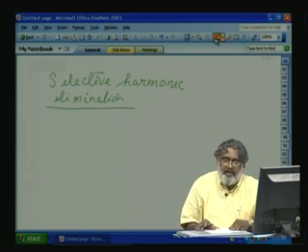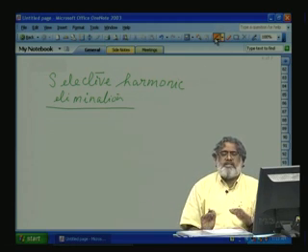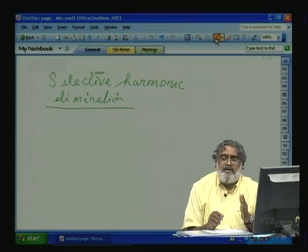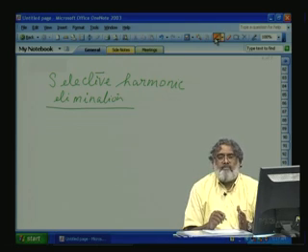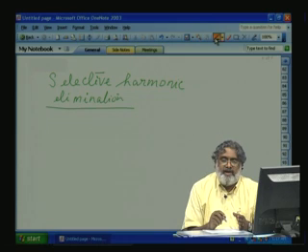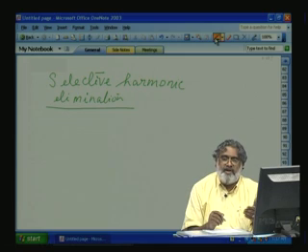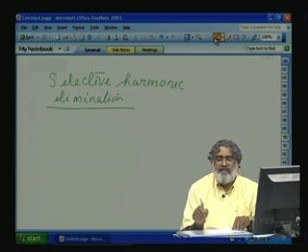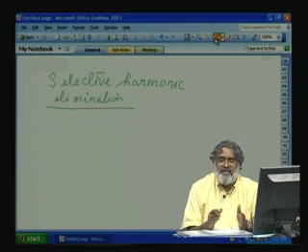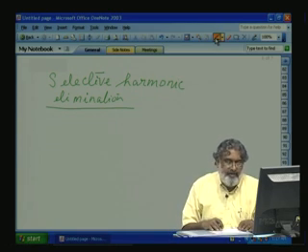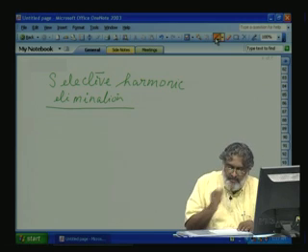Here we are deliberately introducing the notches in such a way that we are trying to get a fundamental sinusoidal variation. So, the notches are introduced such that the positive half cycle, the first 180-degree period, and the second 180-degree period have the correct symmetry of a sine wave. So, how is it introduced? Let us see a typical pattern for selective harmonic elimination.